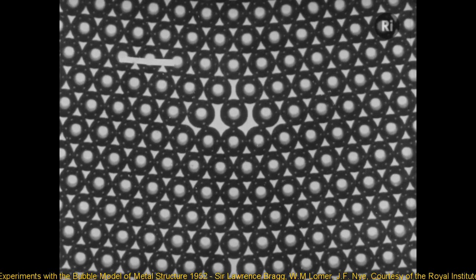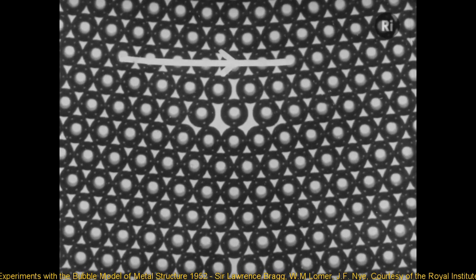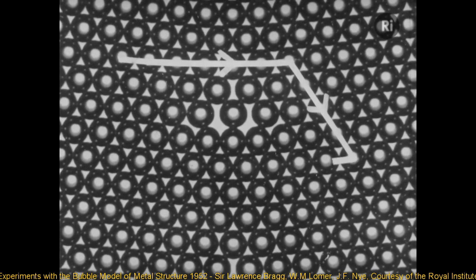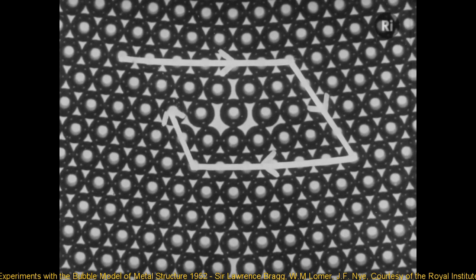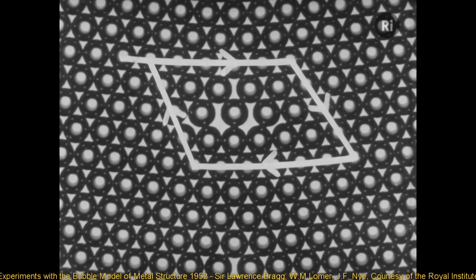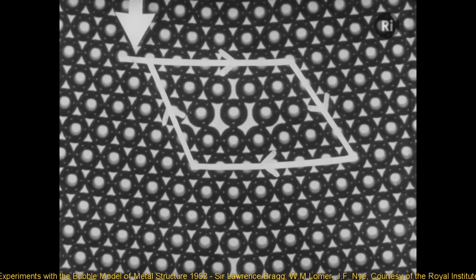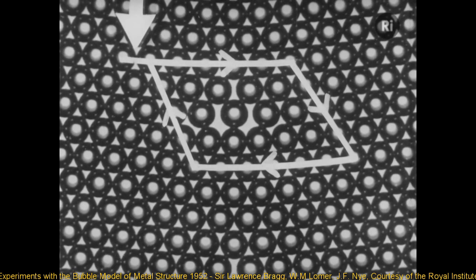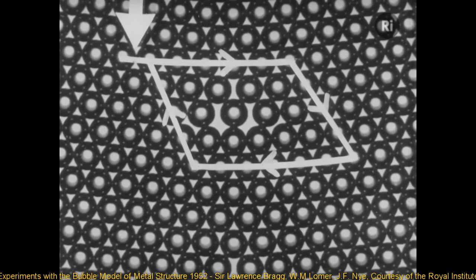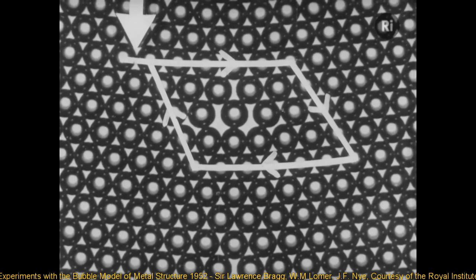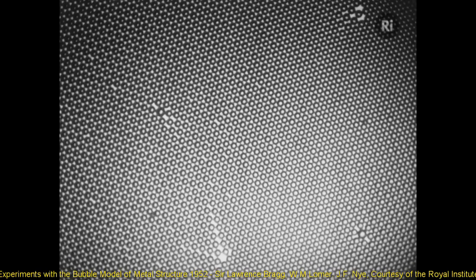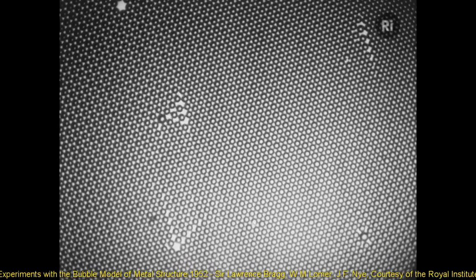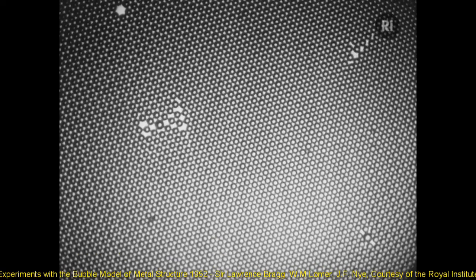In order to determine the magnitude and direction of the distortion caused by these dislocations, draw a line near the start of the dislocation, counting the atoms. Then, draw more lines using the same amount of atoms and following the crystal structure and fully enclosing the start of the dislocation. If done correctly, the endpoint will not be in the same point as the starting point. The extra or missing line shows how far and in what direction the lattice has shifted, and is called the Burgers vector. Substitution defects are particularly difficult for dislocations to shift past, and can rapidly cause dislocations to stack up on themselves.